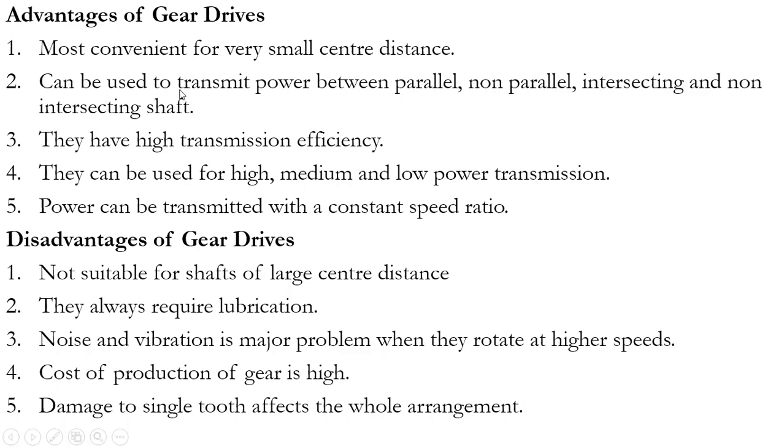Next, it can be used to transmit power between parallel, non-parallel, intersecting and non-intersecting shafts. Whereas in case of belt drives, you can transmit power only between two parallel shafts, here in case of gear drives, you can transmit power between parallel shafts and between non-parallel shafts, as well as intersecting and non-intersecting shafts.